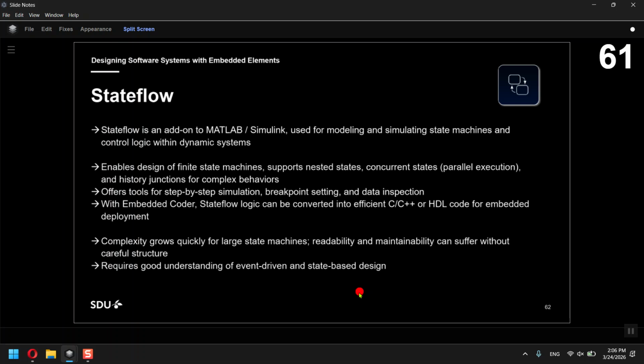What is interesting is that from there you can generate code. If you model your system in MATLAB Simulink and Stateflow, you can use Embedded Coder, and this allows you to generate C++ code. That's what we will try today. There's also HDL Coder, so believe it or not, it can also generate VHDL code for FPGAs, and you can program the programmable logic. That was probably the revelation of the 2000s, where we actually got a toolchain that was able to generate the implementation from the models end to end. It's probably not the most efficient, but it works.